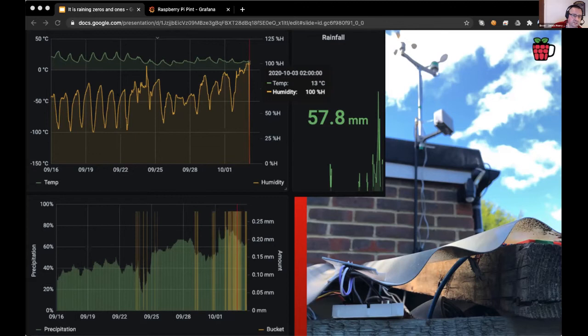And oh, hang on, stop the bus here. My sensor is reporting that it is 100% humid. Obviously my poor deteriorated bit of corrugated plastic, and the way that I'd strung this up here, and the way that the wind and the rain was coming in, had basically soaked my sensor. The yellow lines here show the bucket tips, and this green graph here is how humid it all is. So obviously it's got really wet, and it stopped working. So that was great to be able to ascertain exactly why I'd gone wrong.